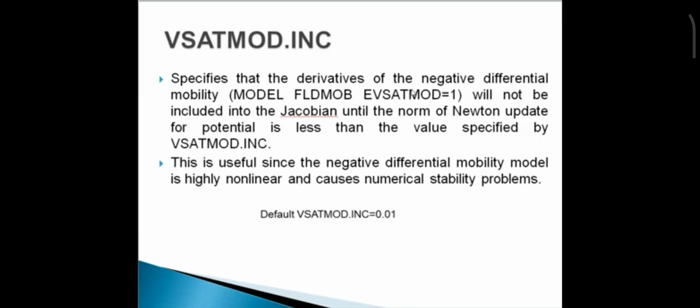This is very useful since the negative differential mobility model is highly nonlinear and can cause numerical stability problems. In my proposed structure in my program, I have set this parameter equal to 0.01.